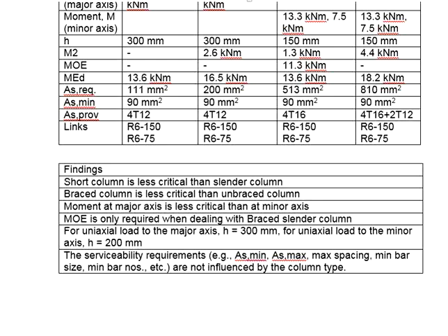You can choose to add the column in the wall, but the column should not be seen. Under these circumstances, you have no choice, so go for the slender column. Now, if you go for the slender column, you are going to need more reinforcement bar in the column.